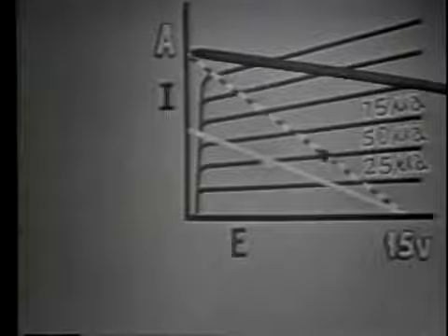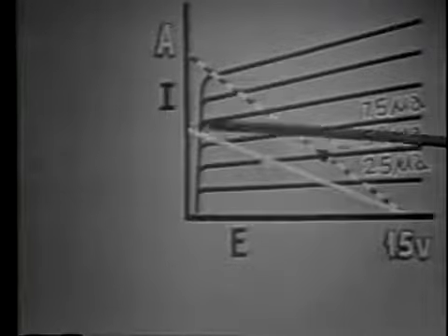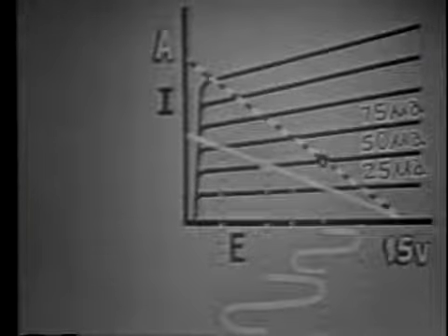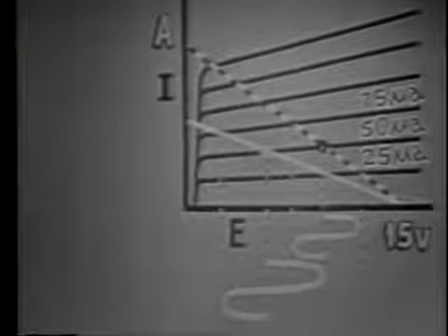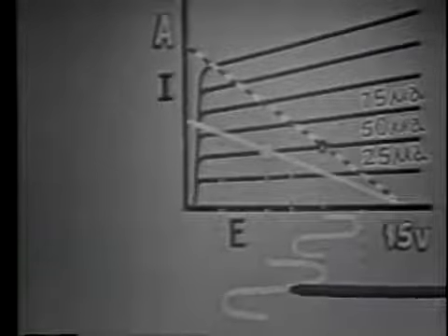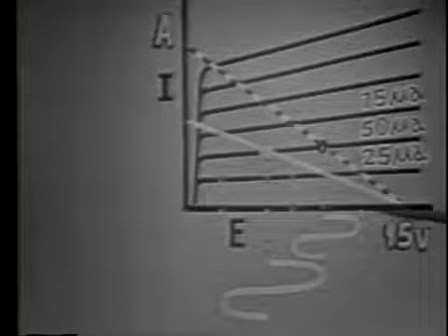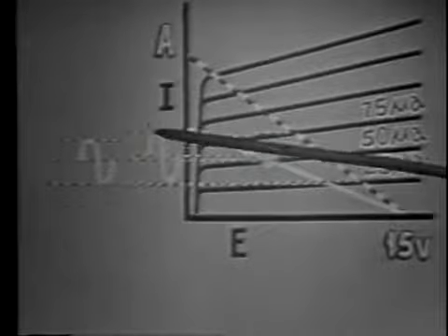If we keep the same applied voltage of 15 volts and increase the load resistor to 4K ohm, the current represented by point A is decreased as shown by the solid line. Comparing the new change in collector voltage to the old change, the swing in collector or output voltage has increased. Making the same comparison with current changes, we see that the new current produced by the new load line has decreased in comparison with the current produced by the load line of the smaller resistor.